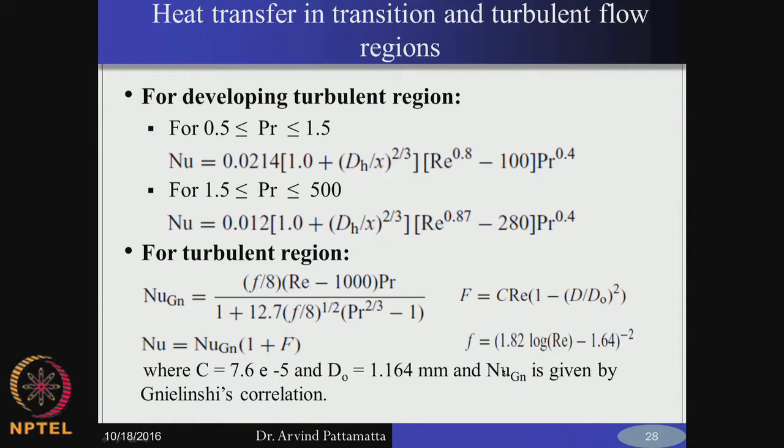So, they have just used it, and again you have to be careful if you have a lot of roughness, you have to replace all this Re with the constricted flow Reynolds number. So, therefore, your f will also become f_CF, that is f calculated based on constricted flow Reynolds number, and the Re here also will become Re_CF, and accordingly your Nusselt number will also get modified.